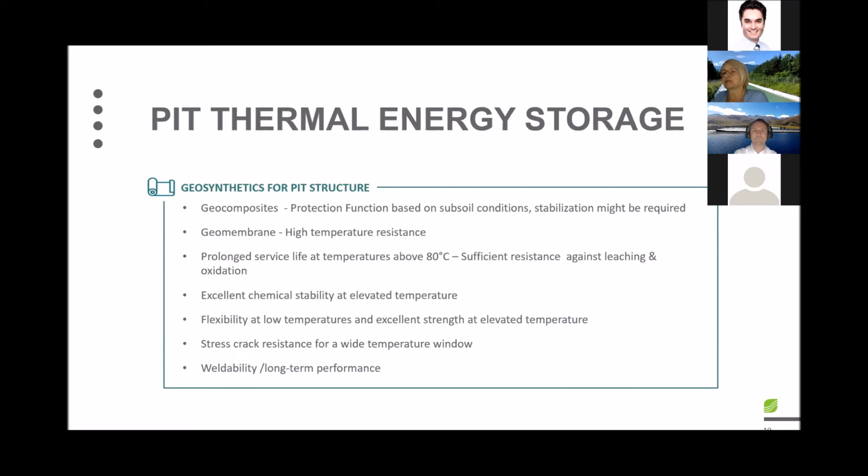What is to be considered is that the material has to offer flexibility at low temperatures, because low temperatures can occur during the filling stage, but also if it is a seasonal heat storage application. But on the other hand, it has to offer excellent strength at elevated temperatures. So both things have to be addressed. And thus the material has to provide functionality over a wide temperature window.